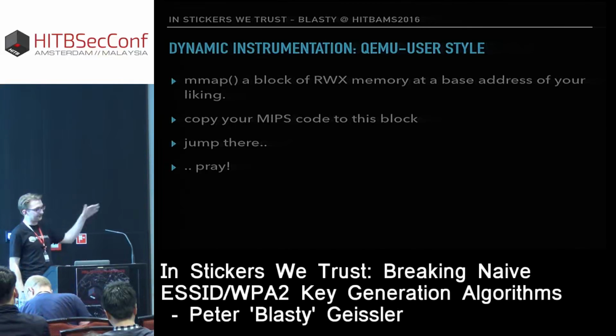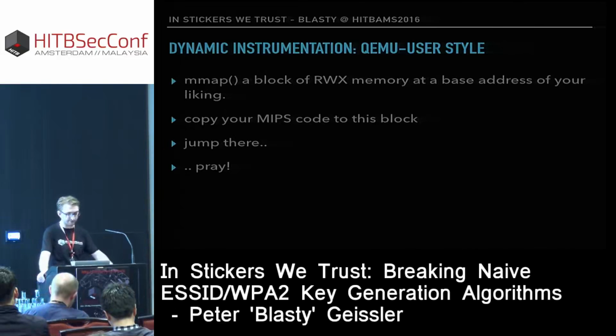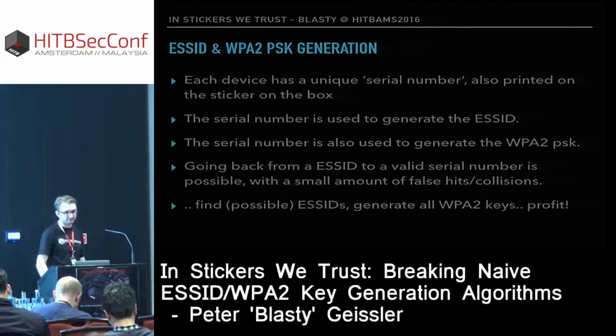And then, well, you can't just jump to the entry point and expect anything to happen. But you can jump to very specific points in the code and get the outcome from there. For example, if you found a routine which does some computation and doesn't touch any hardware or doesn't do anything complicated, then we could just jump to it and get the result from that routine. So this is a very useful way for quickly evaluating some things. But it doesn't give you a whole lot of control. I mean, you could still attach GDB and influence things that way a bit. But it's a bit cumbersome. Of course, you have to write C code. It's also cumbersome.